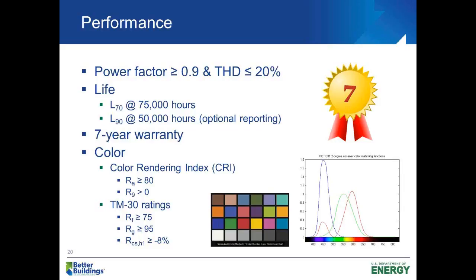That might be a requirement that you still have after this, and LEDs we know to be directional. So that is something that we don't capture here, but it is something that is a refinement that the lighting specifier, that building owner has to be specific and say, look, I really want my replacement, my retrofit kit, to have 7%, 10% uplight as part of the specification. So those are places where you might make a refinement to the specification, but we're not able to cover every single space, every single scenario. So what we provided is just a typical what is required, and it's very well synchronized with the DesignLights Consortium requirements.